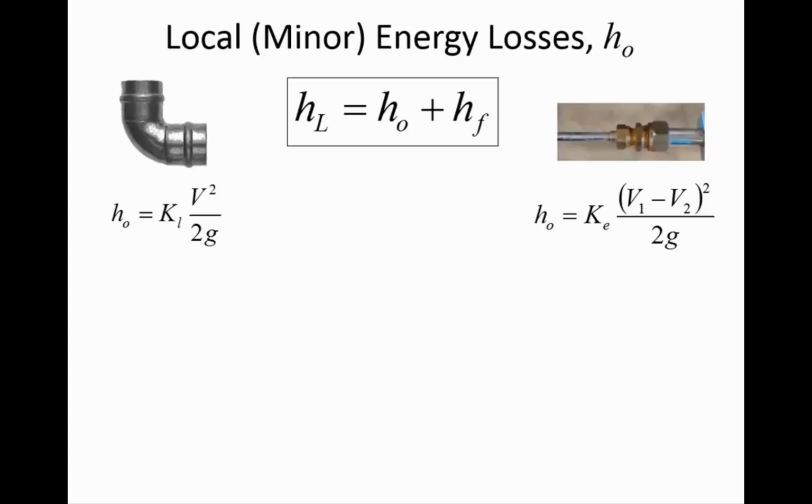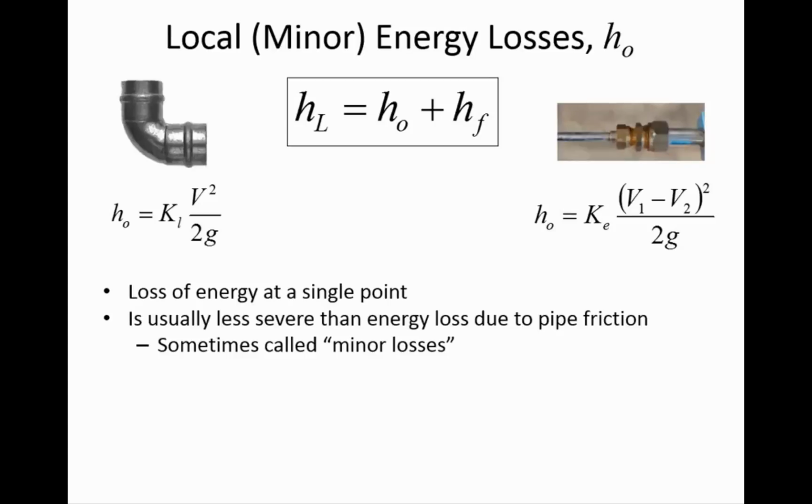If it's a small pipe going to a large pipe like this, obviously you're going to have the water here moving very slow, but then the water there is moving extremely quick, and there's just a jet of turbulence as it enters that pipe. It's almost like water going into a tank, in which case it loses the entire velocity head when water transitions from a pipeline into a tank. And so a really extreme transition in diameters is essentially the same thing. We'll look at some K values on the next couple of slides.